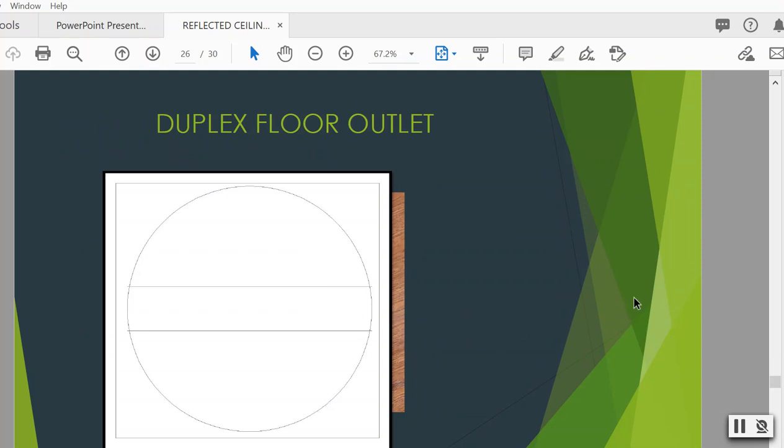Sometimes you need an outlet on the floor. With today's floating and big great rooms, you'll find furniture floating in the middle. How do you get electricity to the lamps that are floating in the middle? Well, often we will specify floor outlets, which are plates in the floor. They have to saw cut into that concrete, lay down that electrical so that you can plug your light into the floor without tripping over the cord from the wall, which can cause a trip hazard. But that really needs to be planned in advance.